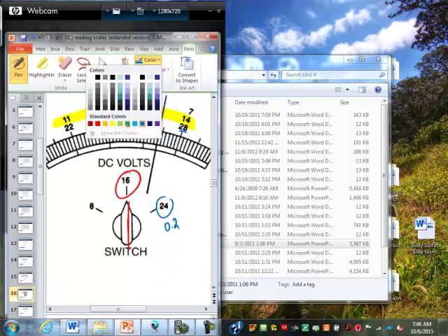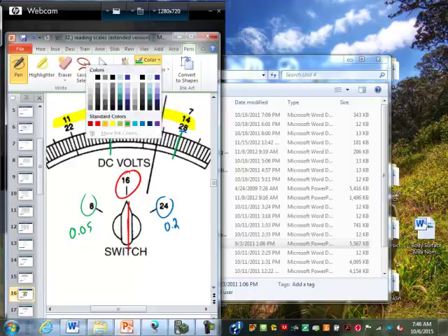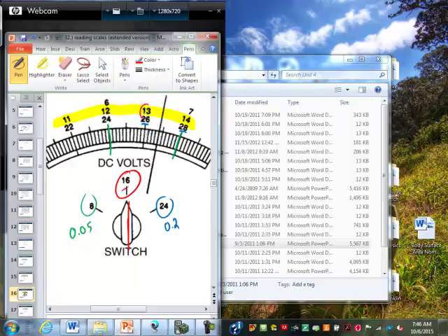If we're on the 0.8 setting, from here to here is just 1 unit, and there's 20 spaces. So that'd be 0.05 is each space. And then, of course, on the 16 setting, from here to here is 1 unit, and there's 10 spaces, so that's 0.1 units per space. Yeah. So this is 13.4. So you were correct. And that is DC volts, that's V. Any questions?